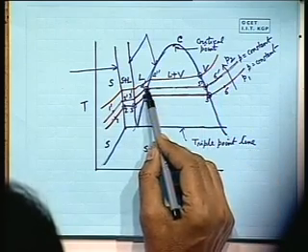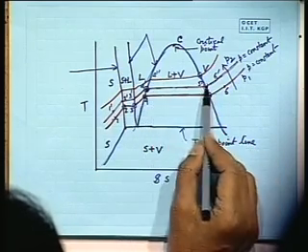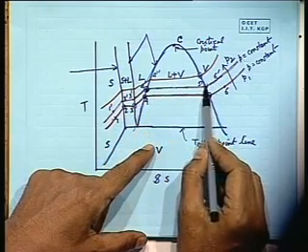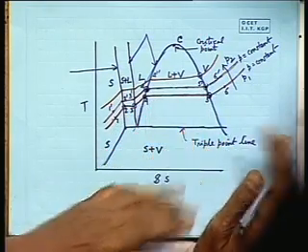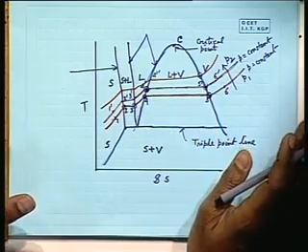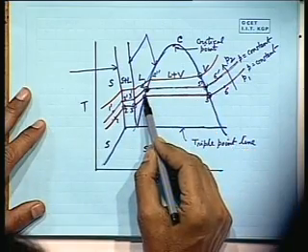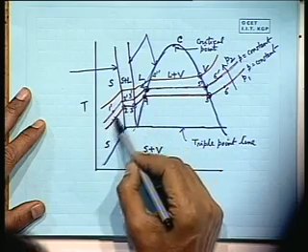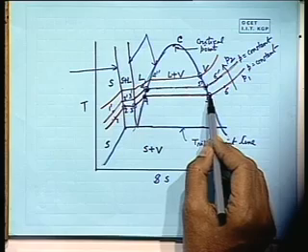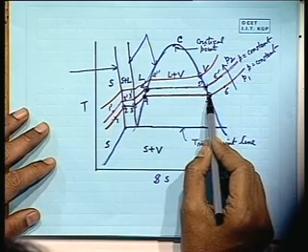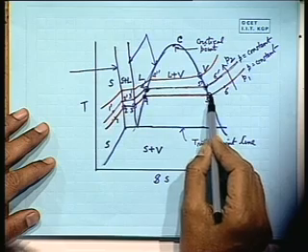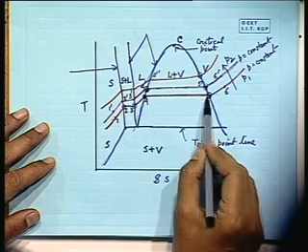That is because at this higher pressure and temperature, the latent heat, which is the difference between the enthalpy at this point and this point, which we will again explain in the HS diagram, is less. Just again I am giving an example: if this line is a 1 atmospheric pressure line, then this is 100 degrees Celsius vapor. So the difference in enthalpy between this and this is the latent heat. That means the entropy changes because of the latent heat absorption.